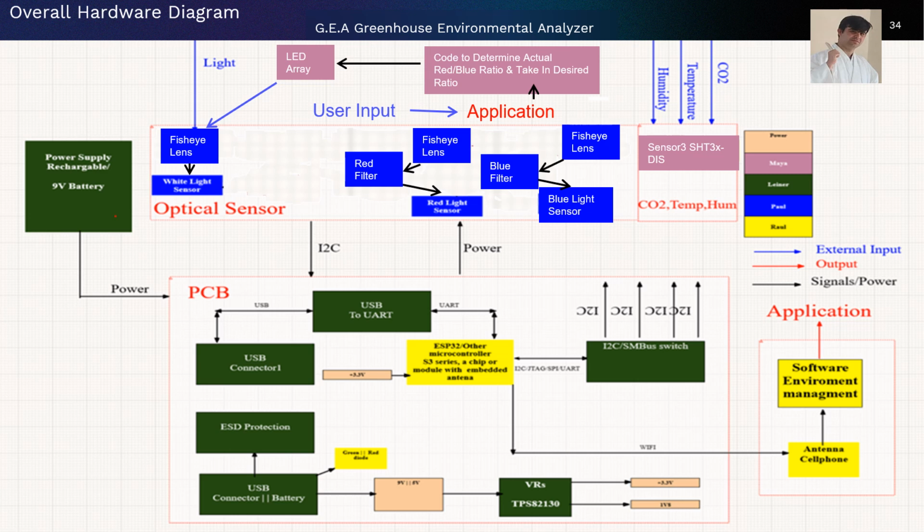This IC splits one I2C line into 4 I2C lines. Why do we need this? Because we have 4 sensors that share the same I2C address. Since they share the same I2C address, we need to use different buses of I2C with this IC, and it does a really good job. We already tried it and it's working properly.